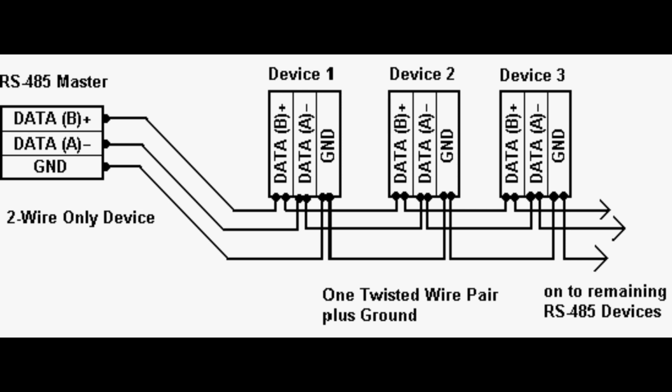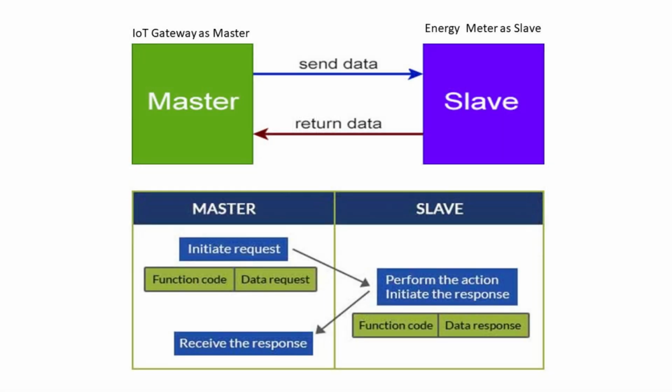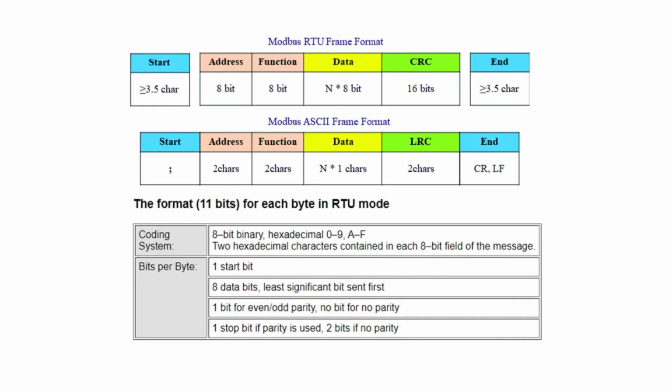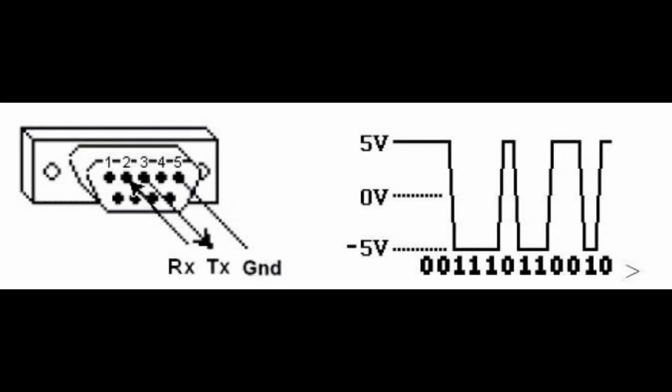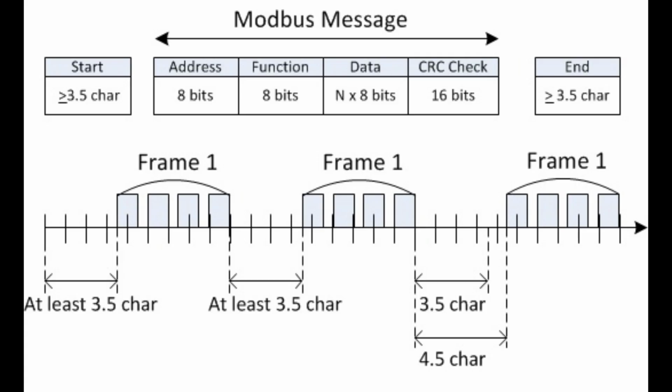Modbus is transmitted over serial lines between devices. The simplest setup would be a single serial cable connecting the serial ports on two devices, a master and a slave. The data is sent as a series of ones and zeros called bits. Each bit is sent as a voltage. Zeros are sent as positive voltage and ones as negative. The bits are sent very quickly.